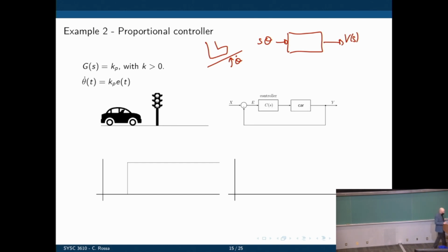That's to say that the car could be simply modeled as a pole, a real pole. So let me not call this MS plus B, let me call this AS plus B. Thinking about a Bode plot, what would this entail? Having one cutoff frequency at a certain point. Past that point, the effects of the input do not affect the car speed that much. So that gives us an idea of how to go about modeling the car. The input to the car is the gas pedal speed, and the output is the speed of the car itself.